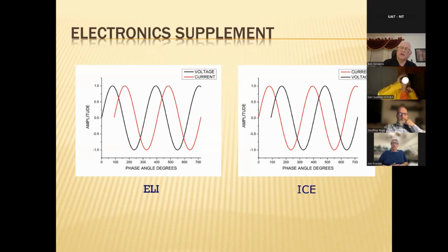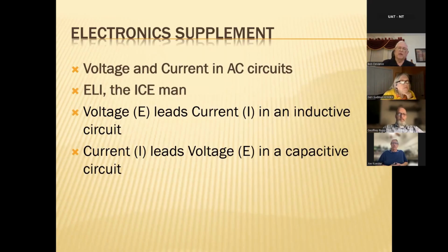So we use this little thing, Eli the Iceman, as a memory tool, basically, to remember how to look at those things. Voltage leads current in an inductive circuit. Current leads voltage in a capacitive circuit. And you will see that on the test.